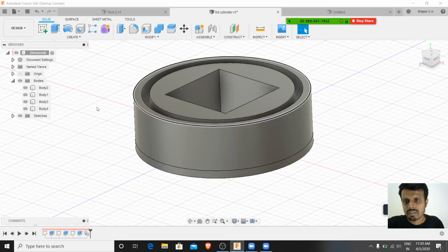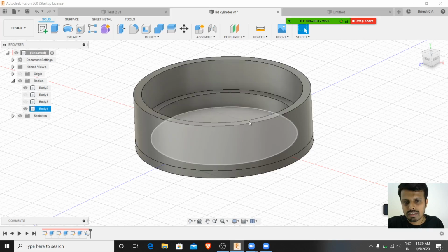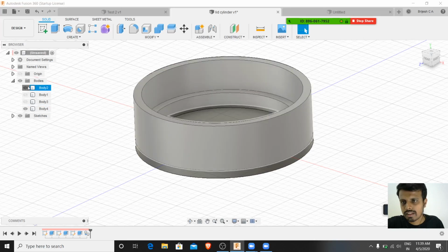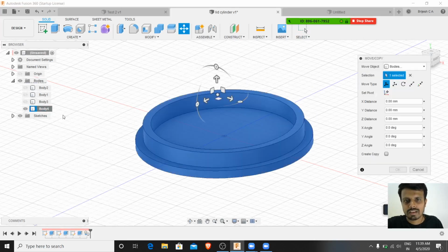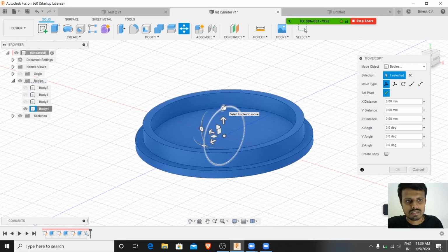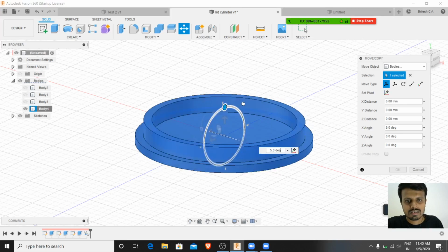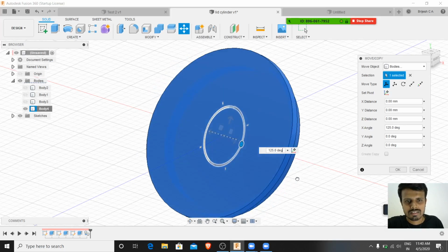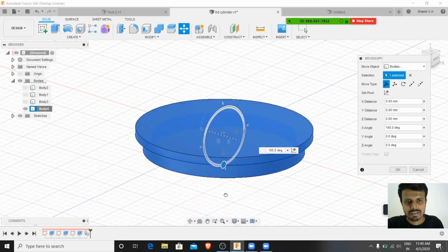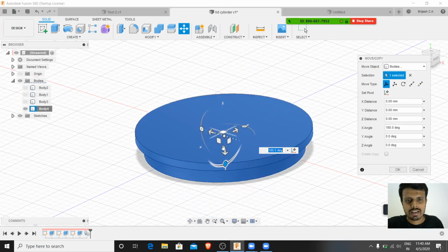Okay. So what you're telling is, if I have to rotate this, I select this, right click, move copy. Now I have to set the pivot point. Click on set pivot point, set it, and then press the green color marker there. Done. Now the pivot point is set. Now you can handle this object. Okay, it is flipped by 180 degrees.